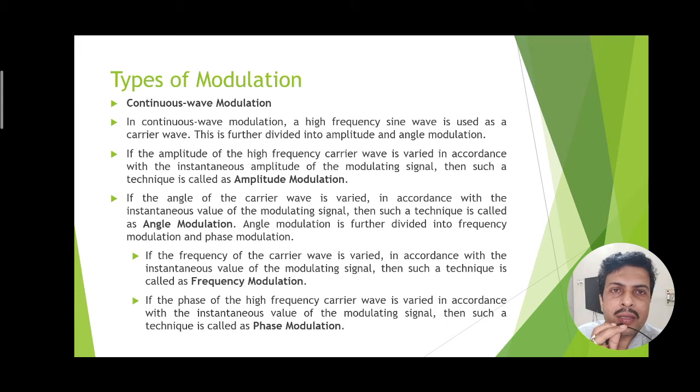Normally, any signal has magnitude, frequency, as well as phase information. So when a message signal shows the variation of information in terms of magnitude with respect to time, and this message magnitude is varying the carrier amplitude, then we call it amplitude modulation. Carrier is also an electrical signal that has amplitude, phase and frequency, all three parameters. But we should remember that the message has information residing only in the magnitude, not in the phase, not in the frequency. So that is why the message signal has to be introduced into the carrier.